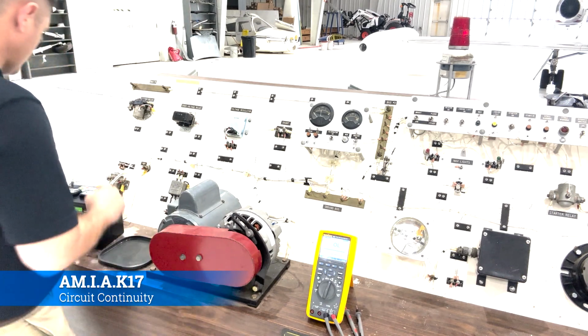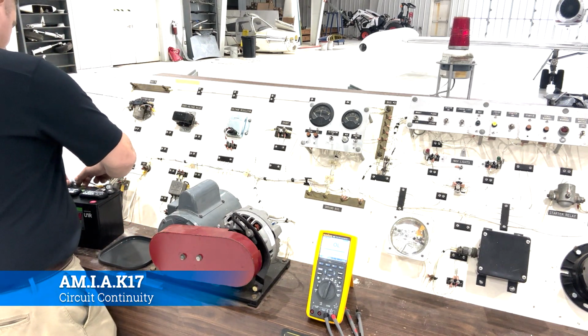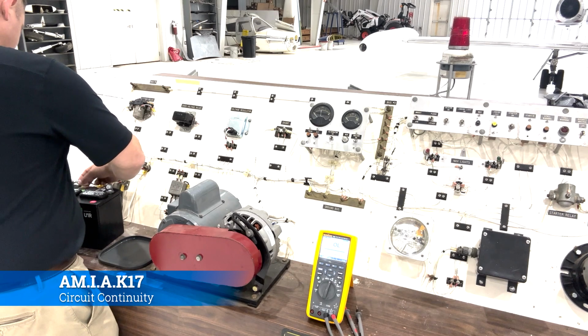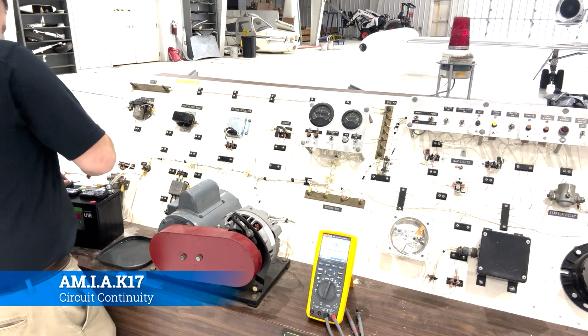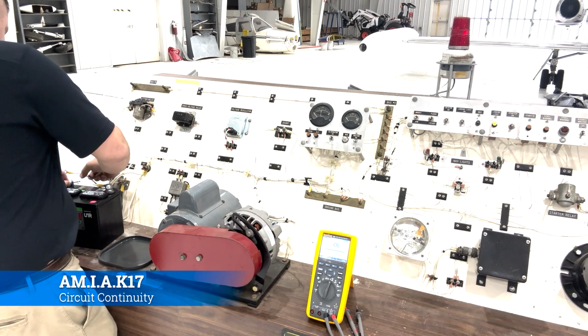You want to test it. Always test your meter and make sure it's working, because the last thing you want to do is a lot of troubleshooting, thinking that everything's okay, just to find out that your meter wasn't working or the alarm wasn't on. Next, never ever work on an electrical circuit with power applied. This one doesn't have a switch, so we're going to physically remove the battery. That's what I'm doing right now.